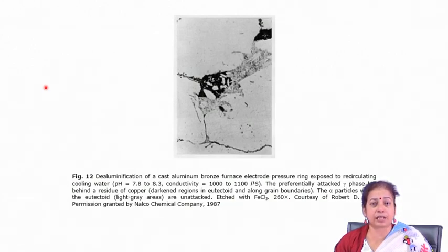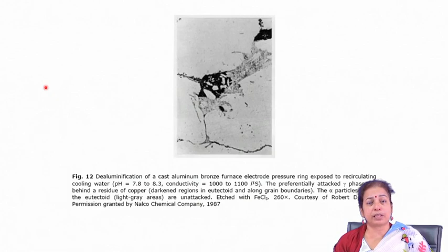These kinds of things can be applied, whatever are applied in combating general corrosion. So, similar solutions can be applied, but it is better that you take care of the overall microstructure carefully, so that there are no grain boundary second phases present prior to its application in the environment.